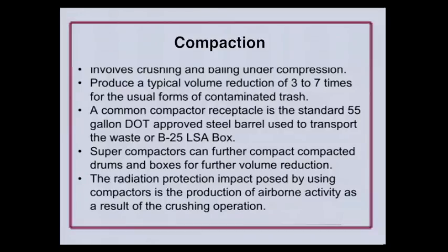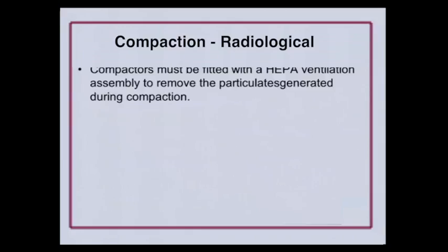Even if it's low level, it's going to stir up or possibly suspend that radioactive material in the air that's being pushed out. And so that right there tells you that you need some type of ventilation. It needs to be filtered ventilation, HEPA, to take a suction on the compacting area and pull the air away and filter out the contaminants.